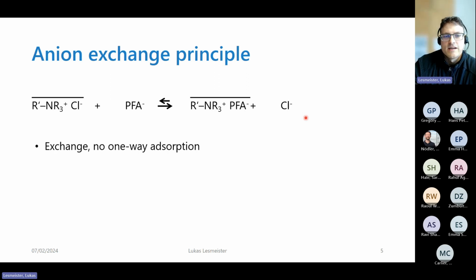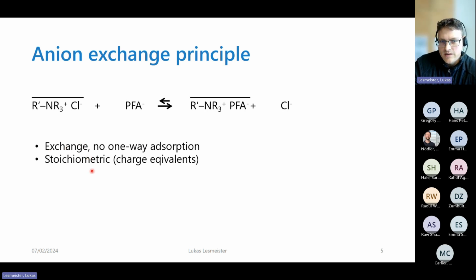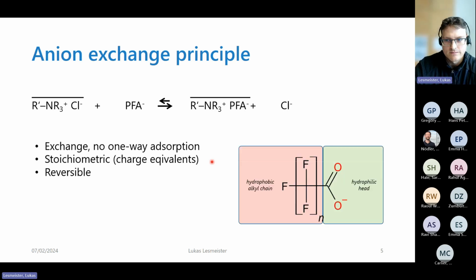Important to note here is that it's no one-way adsorption, such as activated carbon is, but it is an actual exchange that is strictly stoichiometric in regards of charge equivalence, and it is also reversible. That becomes important when we talk about resin reuse and regeneration later on.